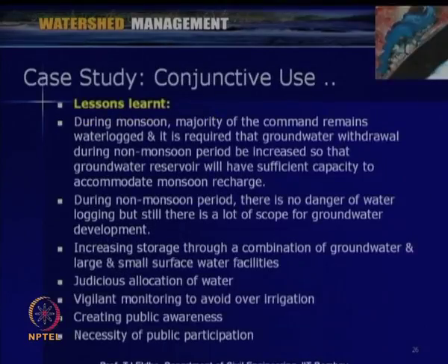Some of the important lessons learned from this case study include that during monsoon the majority of the command remains waterlogged, and it is required that groundwater withdrawal during the non-monsoon period be increased, so that the groundwater reservoir will have sufficient capacity to accommodate the monsoon recharge. So, whatever water is available, more water available during the monsoon season, we want to recharge. That way recharge plans were made for this case study.